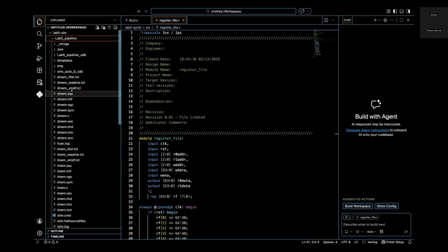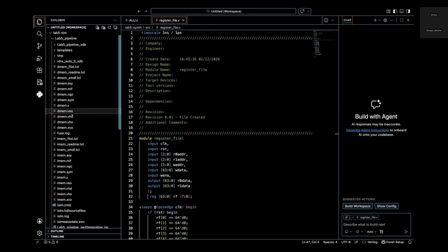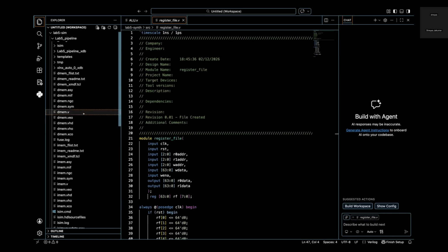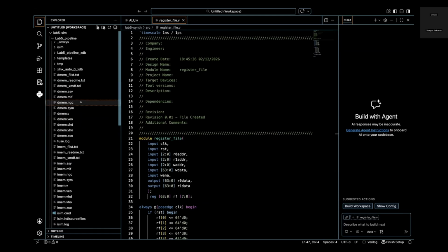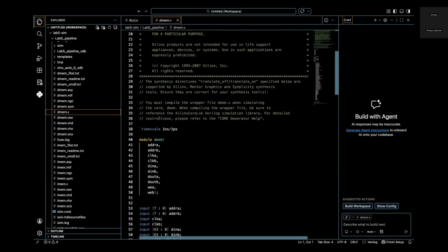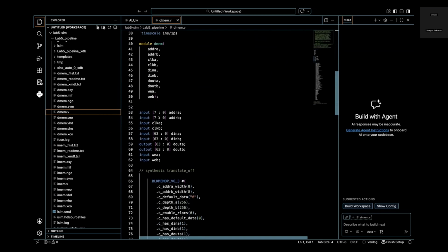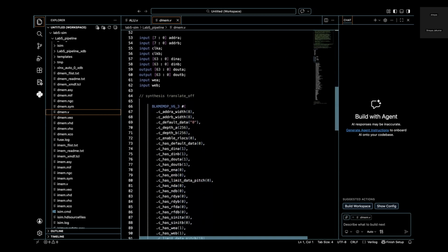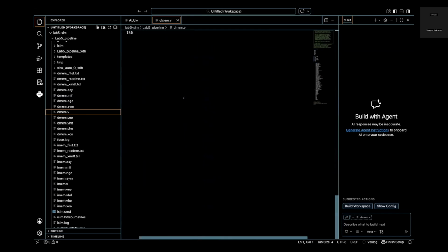This is because, as I specified, we used the core IP generator to generate all these. As a result, there is a bunch of files, but the most important files are the .xco files, which will go into the source folder in the NetFPGA projects in Fedora, and the .ngc file will go into the synth folder. Similarly, the same thing for IMEM as well. So I'm just going to quickly run through this. This is basically a black box.